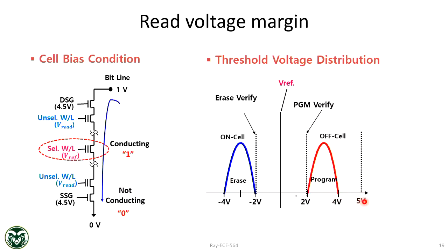So this 5 volt is here as the pass voltage in this array, and then you have margin for reading, margin for program. And why are these margins important? Because during read there is something called read noise. When you read, cell threshold voltage can fluctuate because of noise, right? So that's why we need to keep some margin during read.